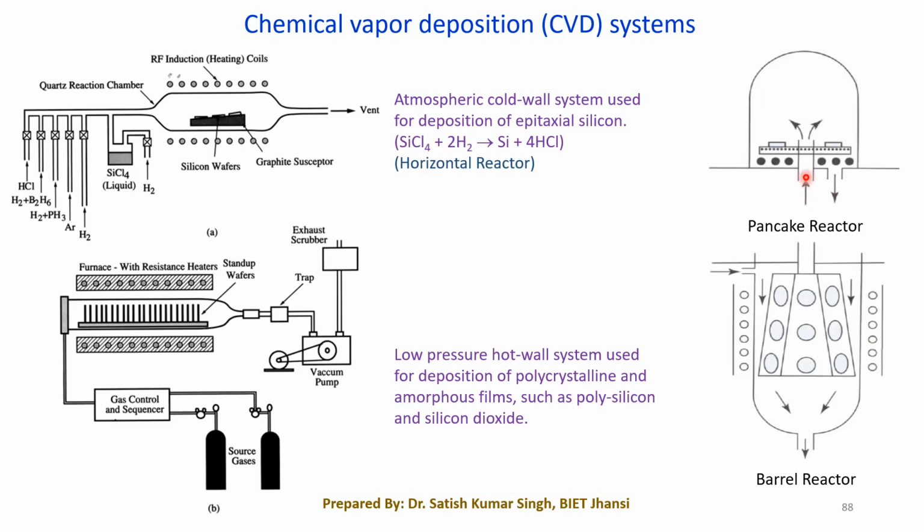centrally mounted. We have a disc shaped susceptor, and onto this disc shaped susceptor we can place the wafers. Then the gas will go like this, and it will be carried to the wafer surface by the side walls, through boundary layers, and then it will make the reaction, and then it will come out through this particular way.